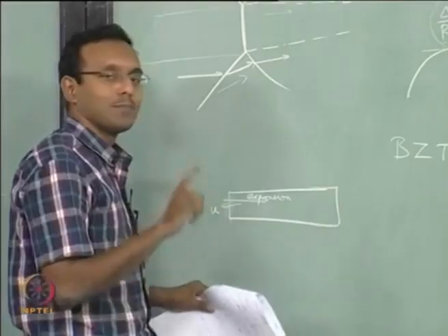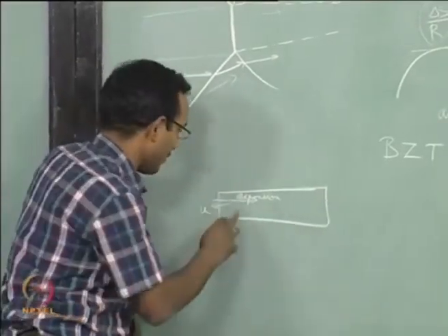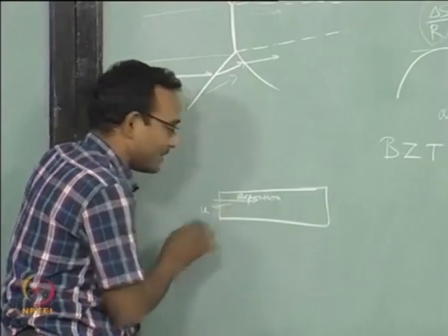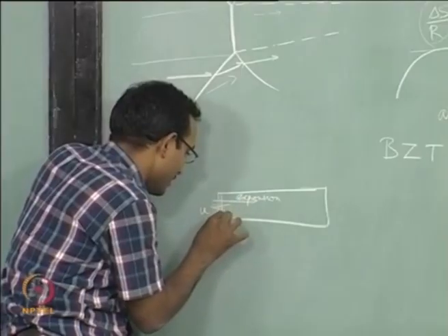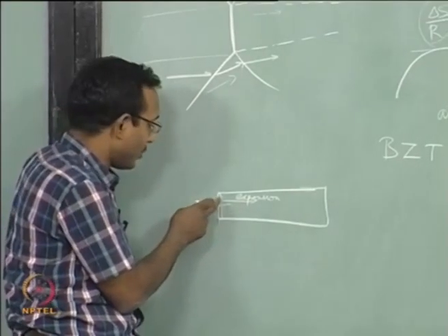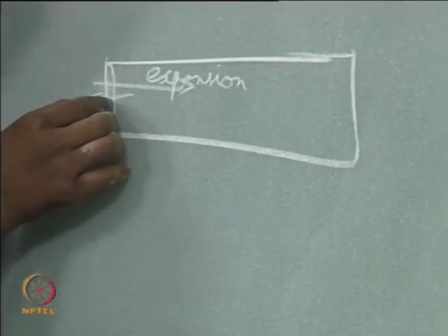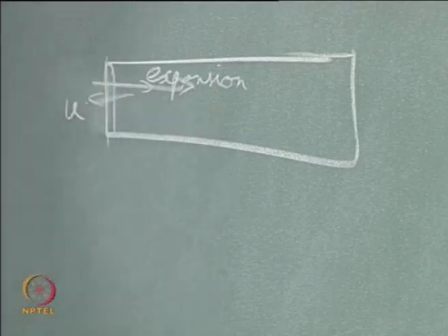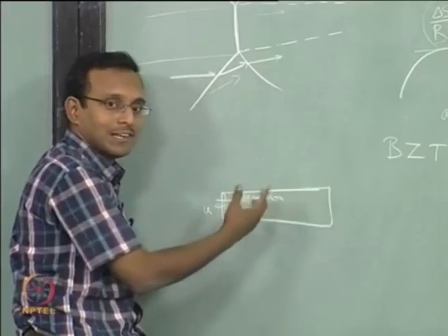Now let us go look at one particular wave like this. Oh, actually I want to tell one more point here. If I open up like this, the very first time the streamline, the particles that are sitting at the edge will see that there is a huge pressure change. So it will send a very strong expansion wave, strong in a sense it will tell that the pressure jump is very high, that is all it will tell. The information that is going in is going to tell you can accelerate very fast this way.